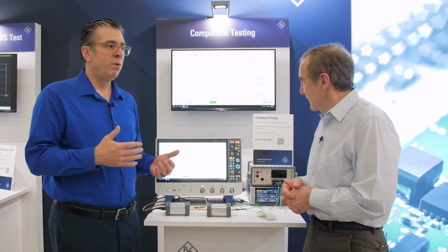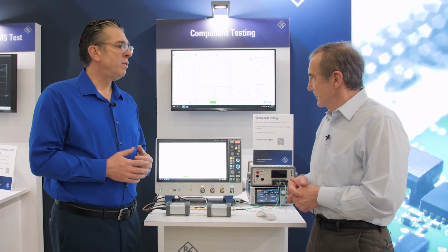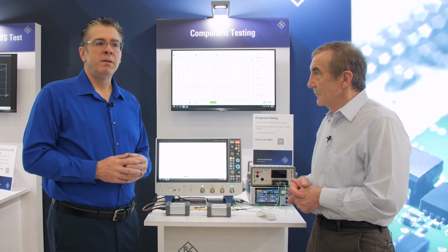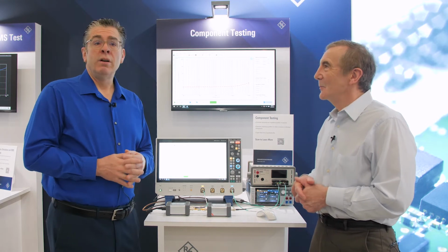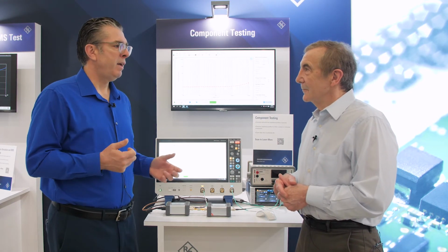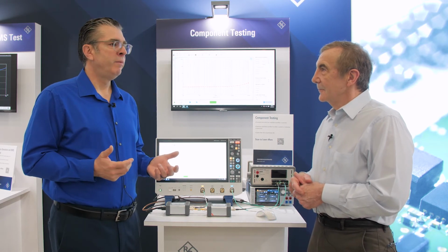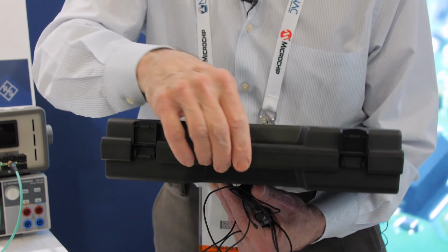You can use this measurement method for component testing, or you can also measure a whole system by looking at the output capacitor of the system to characterize the whole system and make sure it's stable and optimized. On a VNA, you'd be looking at the S21 measurement. When you're injecting energy back into this one, you're able to see what the actual resistance value is as it changes. We're partnering with PicoTest on this demo.